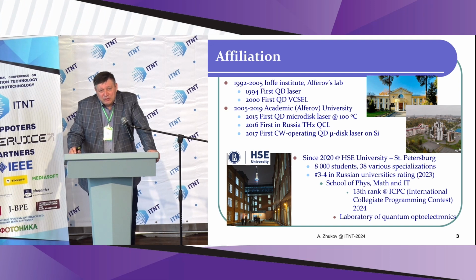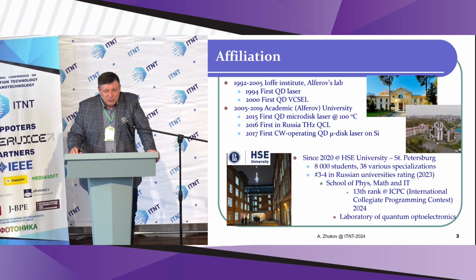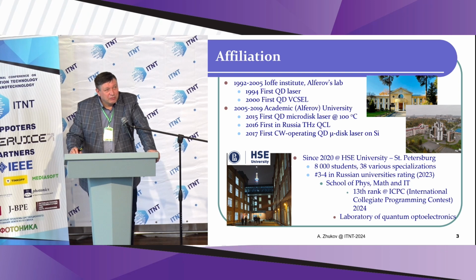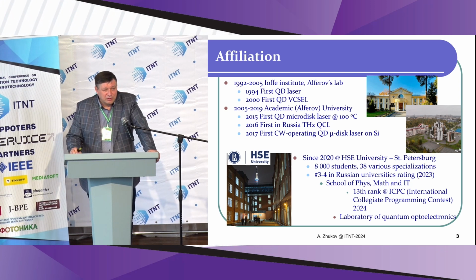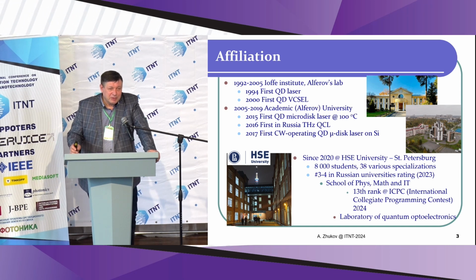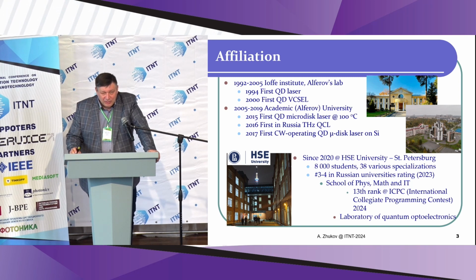At that time, it was just St. Petersburg University of Physics and Technology of the Russian Academy of Science. And here we still focused on quantum dots and their application for lasers. For example, we demonstrated at that time the first quantum dot microdisk lasers capable of operating at elevated temperatures as high as 100 degrees C, which was the world record at that moment.